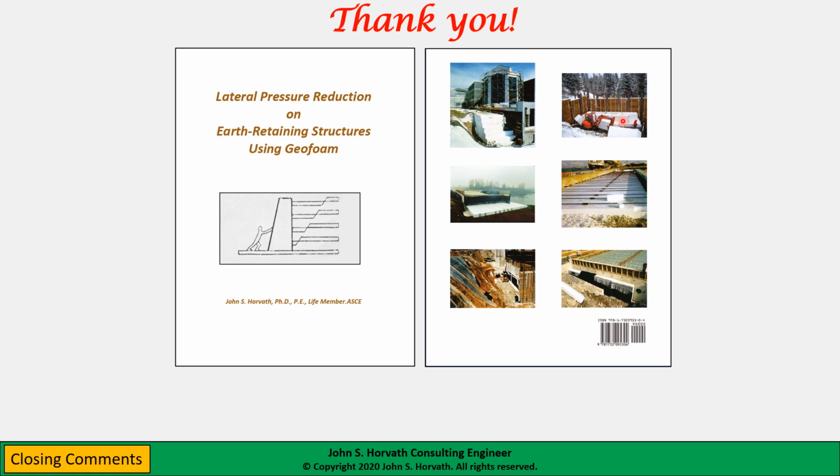This was an interesting little project in Idaho where they used EPS blocks as a lightweight fill behind a soldier pile and lagging wall. Again, this was use of EPS blocks as opposed to, say, a compressible inclusion made sense because they were concerned about slope stability here. This was an abutment actually for a bridge, a small pedestrian bridge. So they were concerned about slope stability.